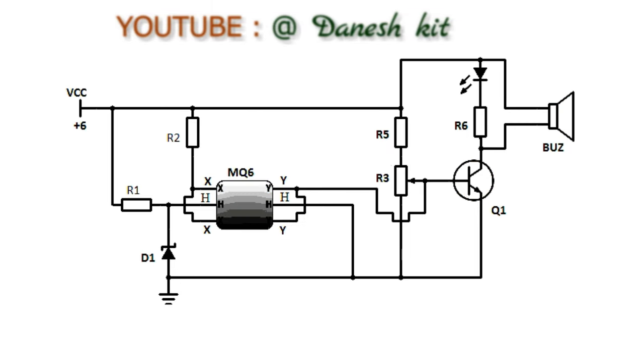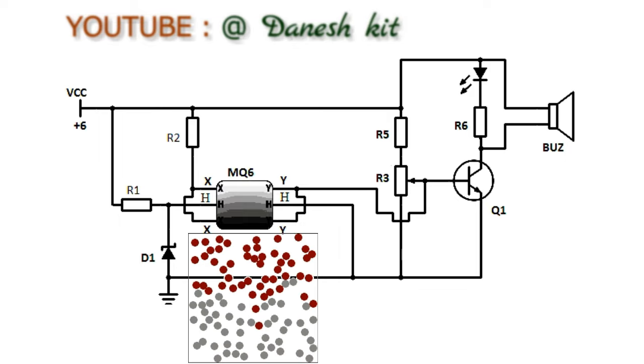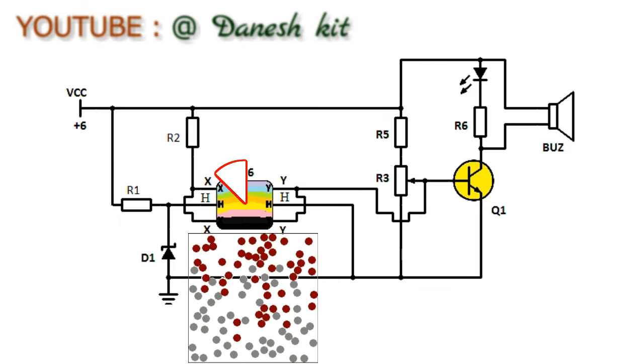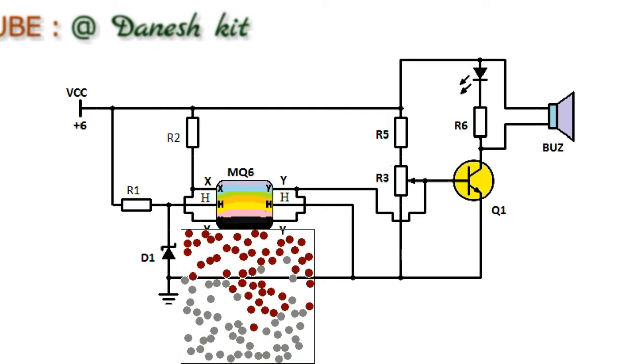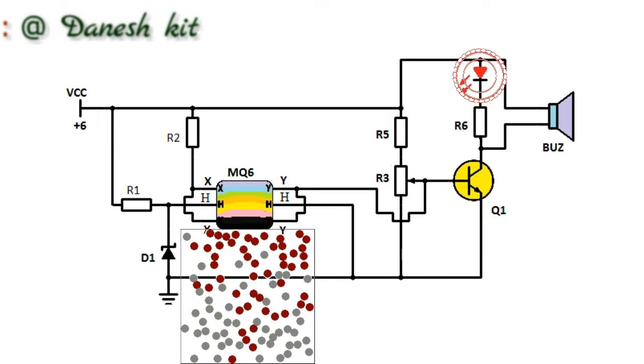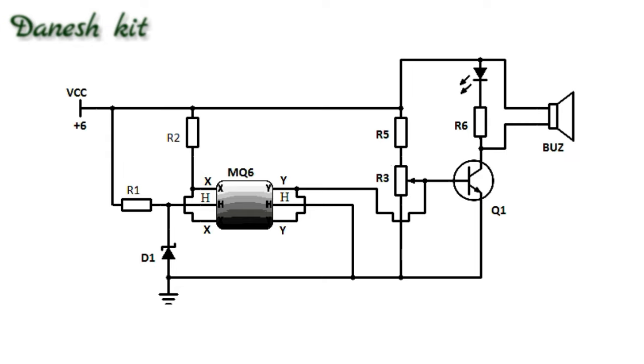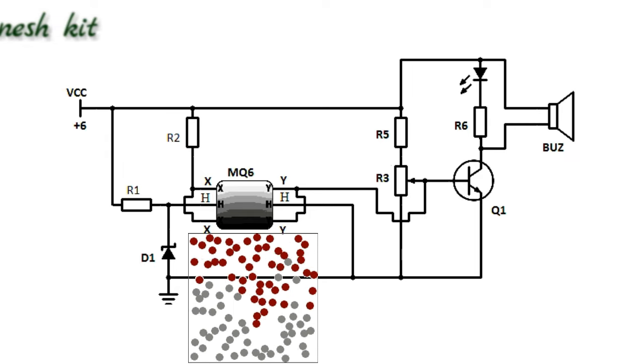After the adjustment is over, enclose the circuit in a suitable casing and install the sensor near the gas stove. Make sure not to include any electromechanical devices in the circuit, as the sparks that might be produced while they are working could cause fire when there is a gas leakage.